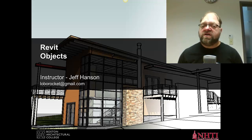So you can think about your design in terms of objects rather than in terms of lines and how you represent something. The representation is already taken care of for you. It's just a matter of getting objects in the right position and controlling some aspects of that object the way you want it to come out. That's really fundamental to what Revit is all about and how you work with it. So it's important to understand that you're working through objects.